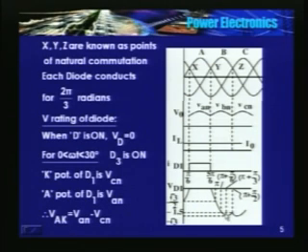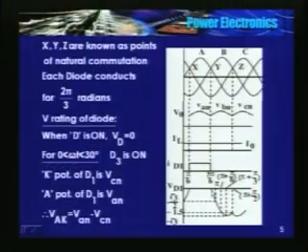If Vm is 100, this comes out to be √3 into 100, which is of the order of 172 volts or so. So at pi plus pi by 2 plus, D3 takes over. Now the voltage is VAN minus VCN. You use the same procedure which we used to draw the voltage waveform across the diode when D2 was conducting, and you will get the same waveform.